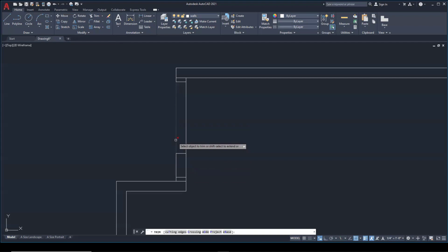And I want to go over here. I'm just going to click that, and I'll click that. And then if it's continuing the trim command, it's asking objects to trim. I'm done trimming, so I'll just hit my enter key or my spacebar key and get out of the trim command. And then let's just put in this frame here.